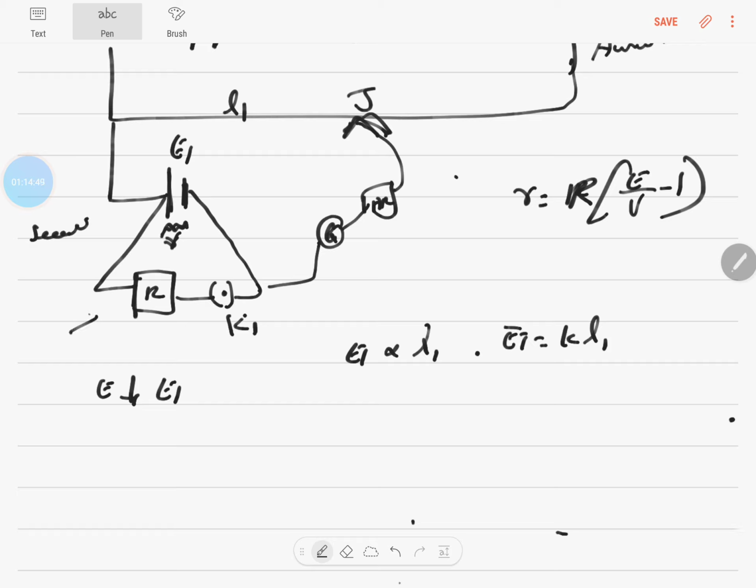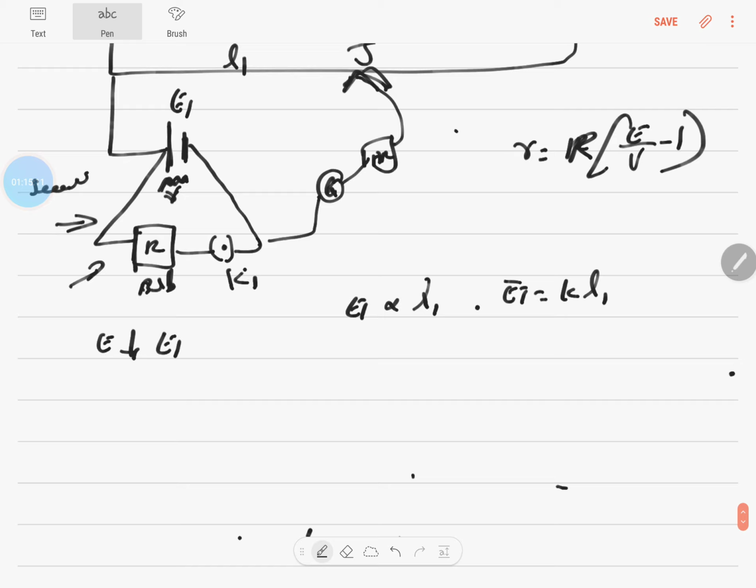The external resistance comes into play, and so now what happens in the secondary circuit? It's like connecting a bulb to it. The internal resistance will show its head because the current starts flowing in the secondary circuit. Because here it's closed, you will still have a current here, even though there's no current in the galvanometer.